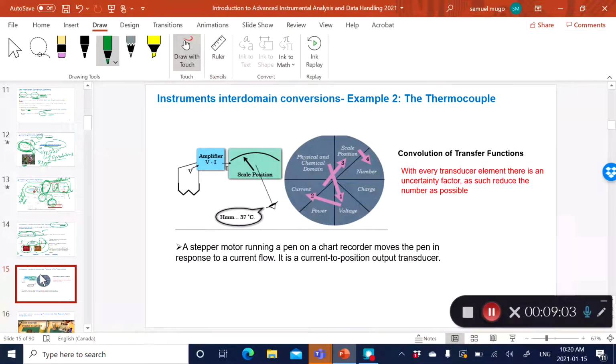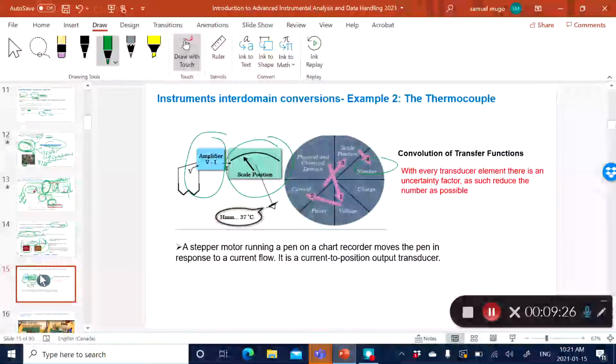And so now you've got the voltage in that case, and of course you can easily digitize it using an appropriate electronic digitizer to give you a number. And now that becomes a number which is a non-electrical quantity in this case. So you can see the input transducer is a thermoelectric effect, the thermocouple, two dissimilar metals joined together, a very simple detector, and then you've got a digitizer at the end, converting the voltage into a digit.